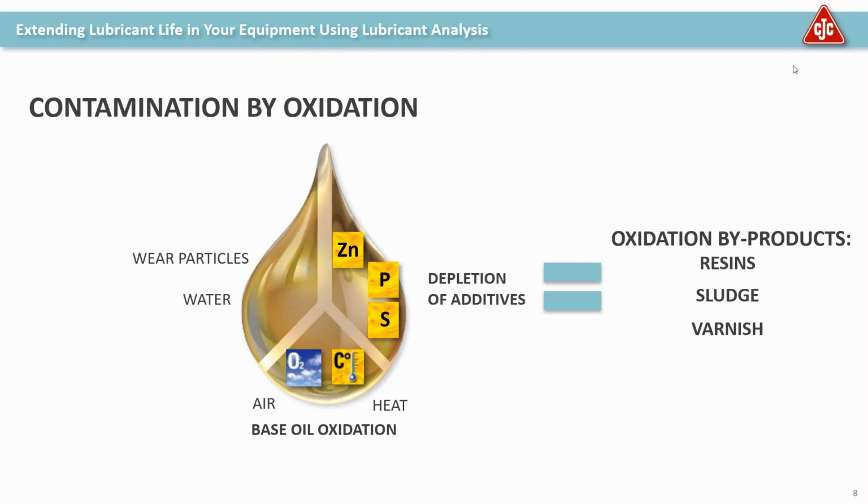Yes. For instance, detergent and dispersant additives, they'll latch onto a particle to keep it finely divided and suspended, so it can be eventually filtered out, which you want it out in that case. Oh, of course, yeah. If it's degraded, it's not doing the job, and oftentimes they act as a catalyst to cause even more degradation. Exactly.